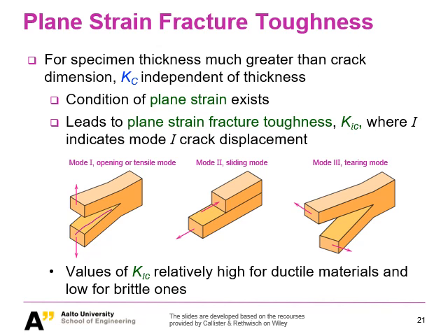And more, if you just apply still a shear, but not in this longitudinal way, but more in a horizontal way, or you're doing a tearing, you can see it from here, and you will get another fracture toughness value. And for a common material, you can imagine these three would be different.